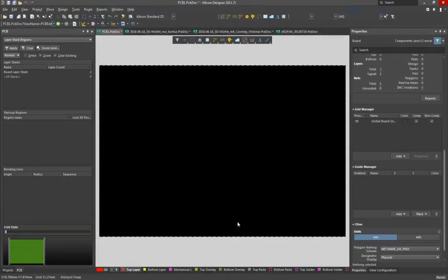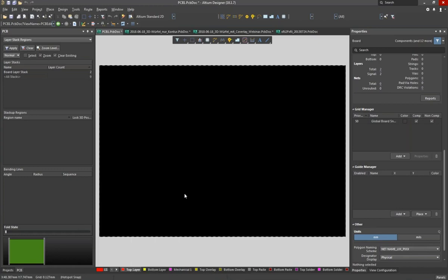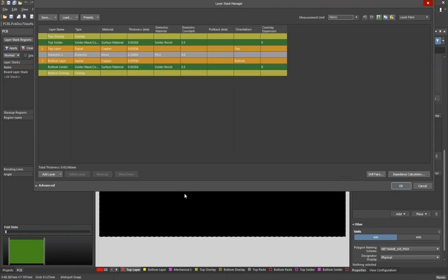Then you will find already the stack-ups to be imported into ORCAD and Allegro, as well as the stack-ups which can be imported into Altium. And a more general format is the newly created IPC 2581 format. So this is already on our website in one or other version. We're not fully completed yet, so we are still working on it, but there are already some of those stack-ups which we already provide in PDF formats for several years, transferred into the different EDA-tool specific versions.